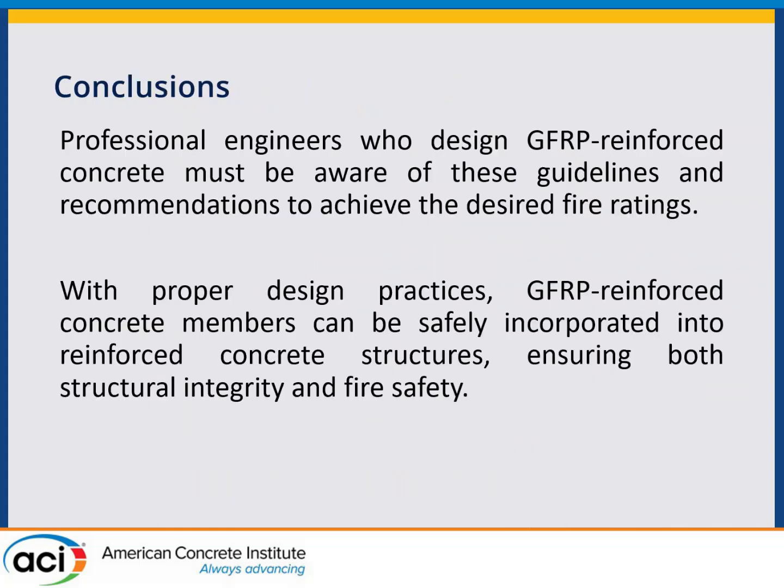So generally, this is my thought. You really need to understand what's going on, as I emphasize. It's really about the bond, and in fire you're going to have basically an unbonded tendon that's anchored at the ends. But those are fine structural systems. And really all we need to do is to prevent the building from collapsing. Now maybe if you want to design so you can have it retrofitted, you would use a different parameter, but most of our fire design codes are all about saving lives and making certain the buildings don't fall down.